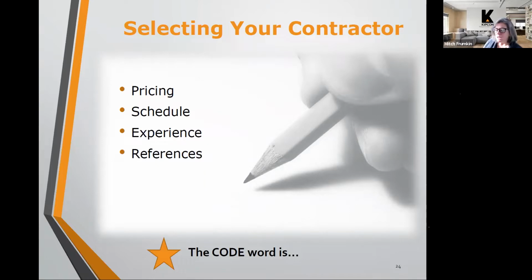Surveys are always nice. They're not necessary for the basic roadway project. As I mentioned before, we'll often rely on satellite imaging if there's nothing else available. And credentials of the engineers: a professional engineer, whether they are a geotech or site work, their area of expertise, any kind of site work engineer probably has the knowledge base to do a pavement project. So I hope that answers your question.